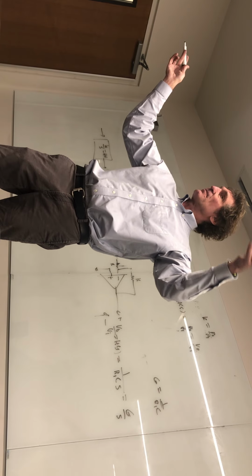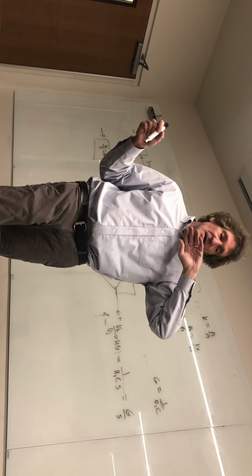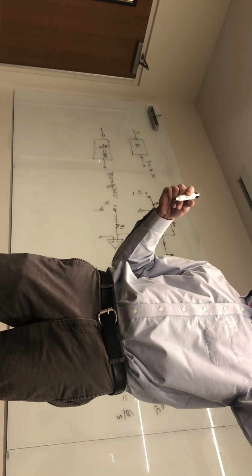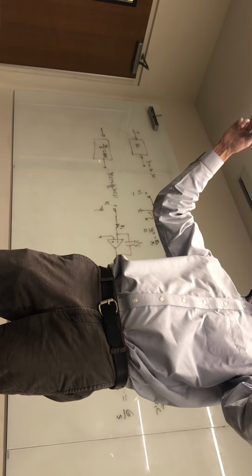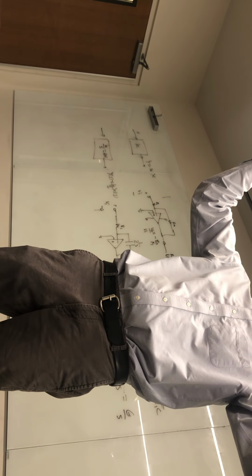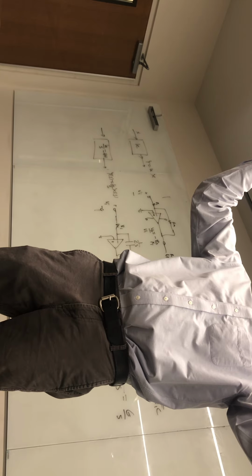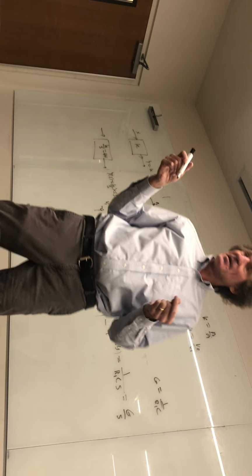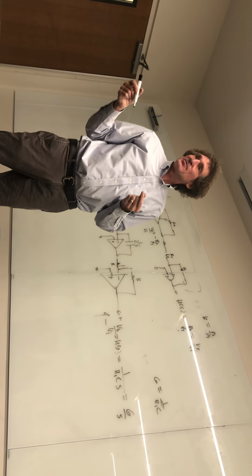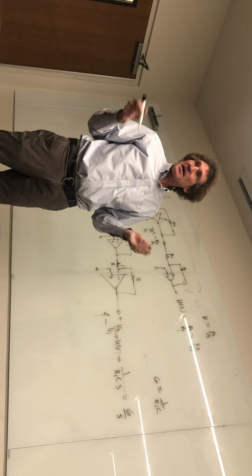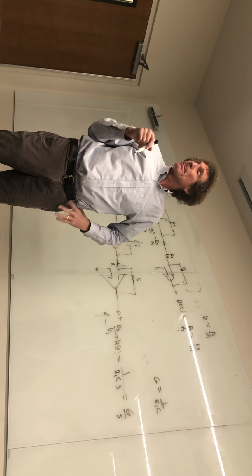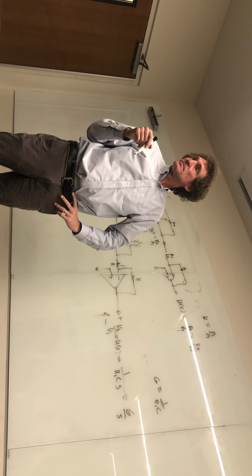And by the way, once you get the profile, the power versus frequency, of your speakers, don't put them up to the point where they distort. Then once you have that function, whatever it is, you take 1 over that function and multiply it before it goes into the speakers, and then you get flat sound. I wish I'd had a couple of speakers here to show you. Get dirt cheap speakers, do this on it and invert it, and then we could do a digital equalizer, and you could see the sound is crystal clear, it's beautiful.